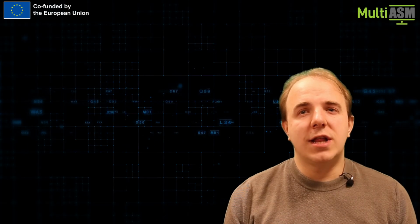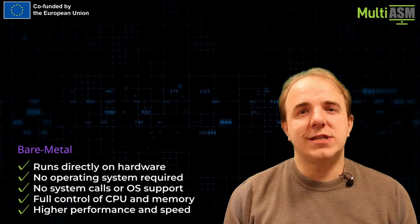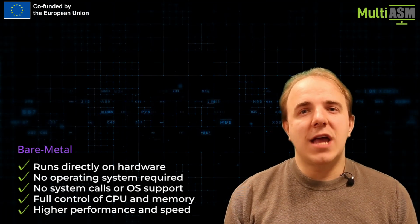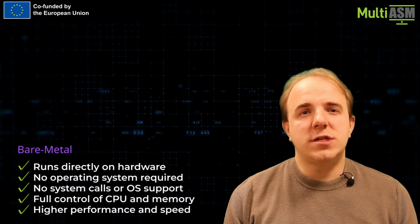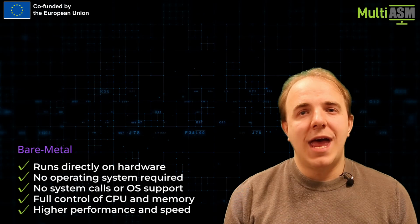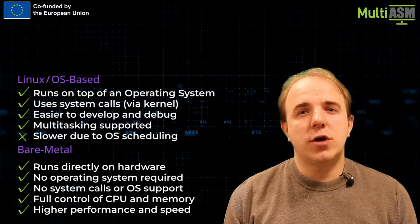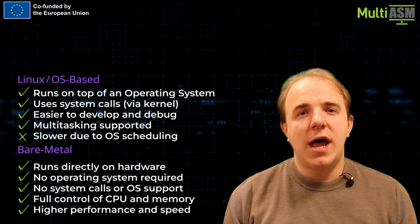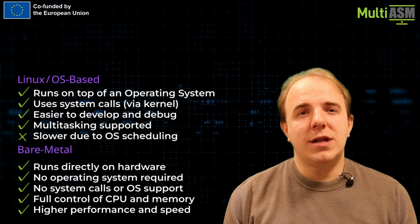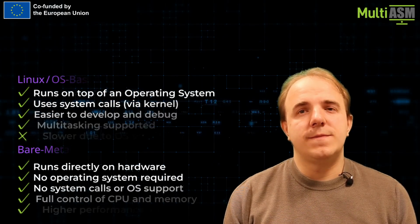Not all programs rely on an operating system. Bare metal programs run directly on the processor, without Linux or system calls. They execute immediately after system reset and are responsible for hardware initialization, memory setup, and stack configuration. This approach offers higher performance and full hardware control, but it also requires deep knowledge of the processor and peripheral address space. Bare metal development is commonly used for bootloaders, firmware, and real-time systems.